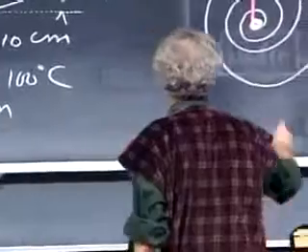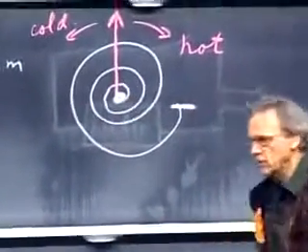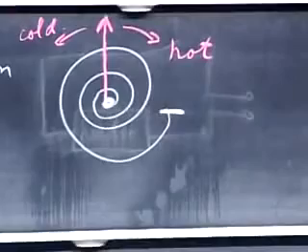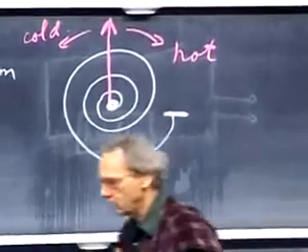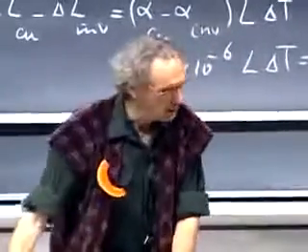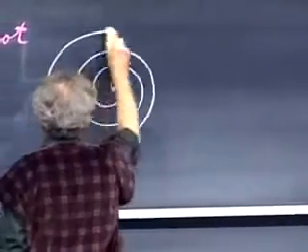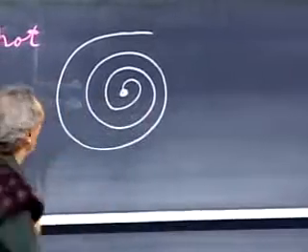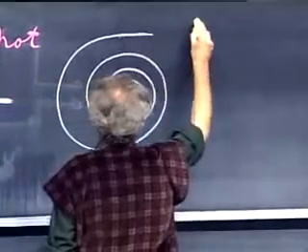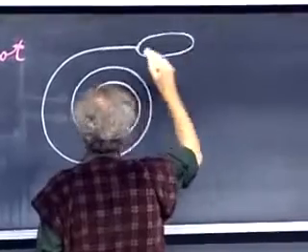Your thermostats in your dormitories of your heating systems and also perhaps of the air conditioning systems almost all have a coil like this in there. It's an extremely ingenious device. It has a coil, and at the end of the coil is a little glass tube, only 1 centimeter large, and there is mercury inside. So the coil is like this. Bimetal. And at the end here is a glass container, and there is some mercury.